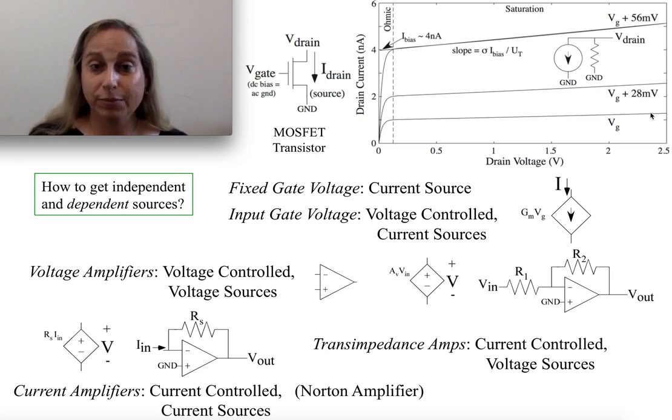This is precisely one of the concepts that shows up: transistors are fundamentally current source type elements. And that turns out to be really interesting. Also, by changing the gate voltage, I'm changing the current source. You think to yourself, well, wait a minute. That means for a fixed gate voltage, a transistor acts like a current source. Now I could make it better or improve it, and there are all sorts of conversations to be had there. But fundamentally, it's a current source.